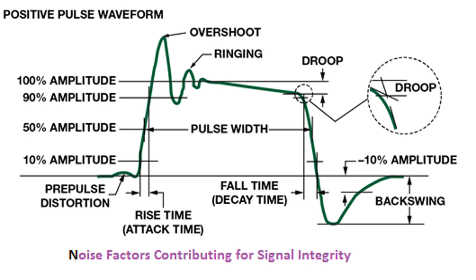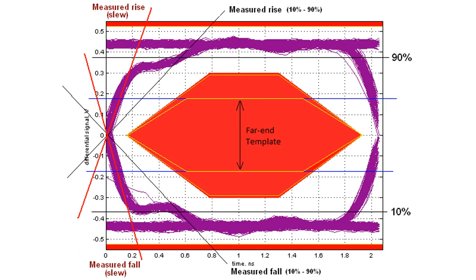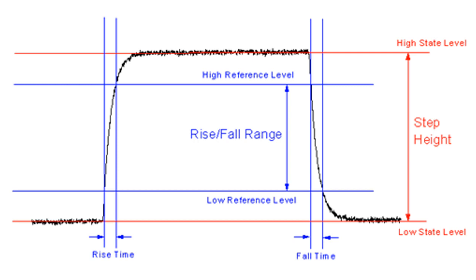The most important cause of signal integrity issues in a PCB is faster signal rise times. When circuits and devices are operating at low to moderate frequencies with moderate rise and fall times, signal integrity problems due to PCB design are rarely an issue. However, when we are operating at high, RF and higher frequencies, with much shorter signal rise times, signal integrity due to PCB design becomes a very big issue. Fast signal rise times and high signal frequencies increase signal integrity issues.